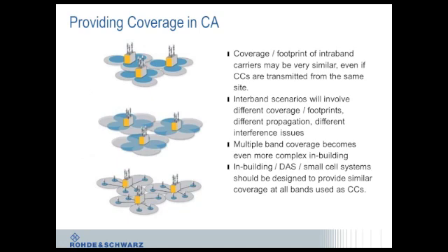The first of these is essentially to try to provide more or less completely overlapping coverage for every band or every carrier in use. This is somewhat roughly depicted in the top diagram. In other words, the cell boundaries for, say, my 700 megahertz and my AWS spectrum would essentially have, as close as possible, 100% overlap. This sounds like, and in many respects is, a perfectly rational and sensible proposal, especially in the case where I can co-locate the eNode Bs, the transmitters, the antennas for each band, since this will obviously make it easier for me to provide identical or nearly identical and overlapping coverage.